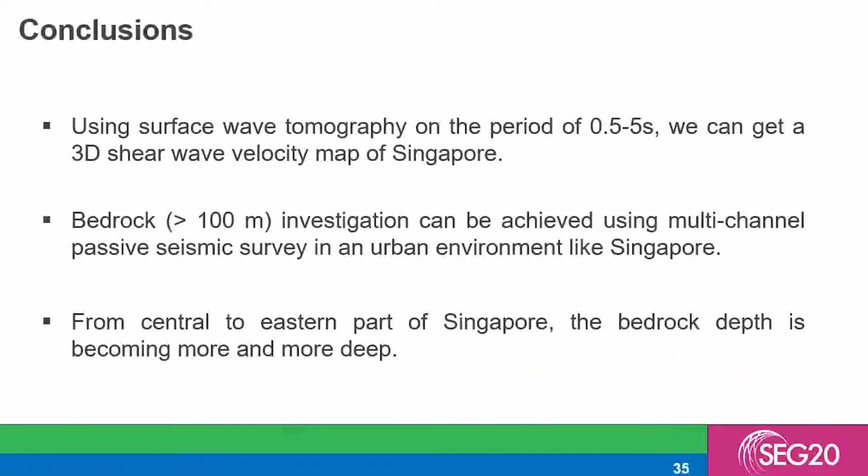Firstly, we use surface wave tomography in a period range of 0.5 to 5 seconds, and we can get a 3D shear wave velocity map of Singapore. And secondly, bedrock investigation can be achieved using multi-channel passive sensing surveys in an urban environment like Singapore. And thirdly, from central to eastern Singapore, the bedrock depth is becoming deeper and deeper according to our tomography result and multi-channel passive sensing